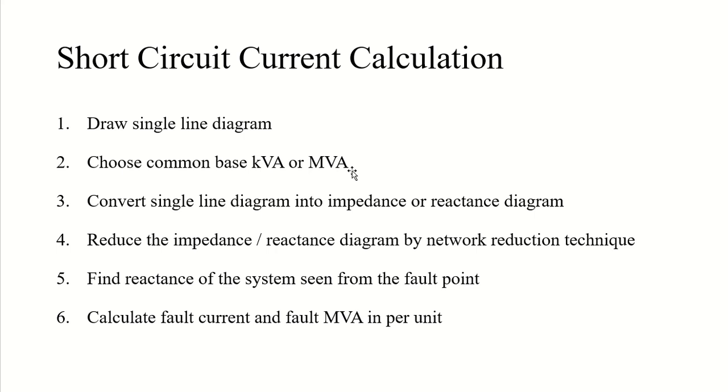But the fault analysis is done by network reduction techniques. And if you have taken the circuit and network classes, you might remember Norton, Thevenin, Millman's. Those are your network reduction techniques. Now this three-phase symmetrical fault is the balanced nature of fault. Always remember, here we are only going to talk about the symmetrical faults, because the chapter is all about symmetrical faults.